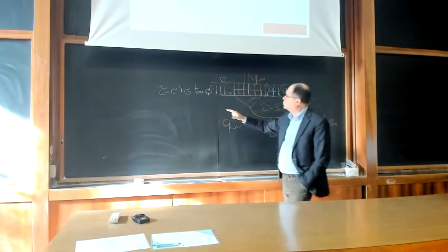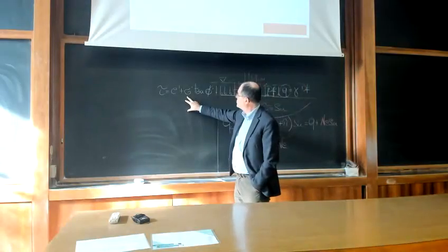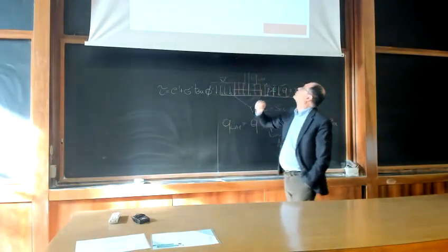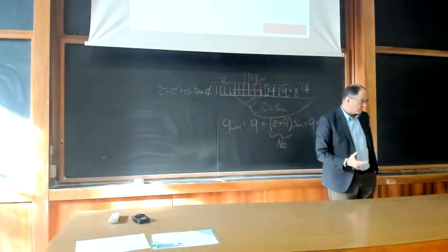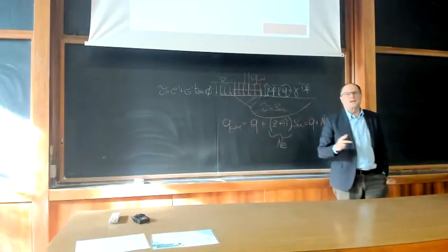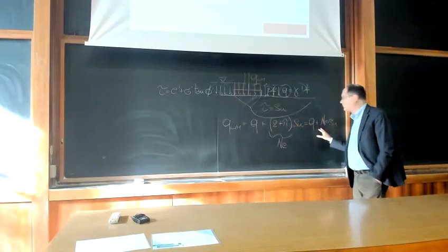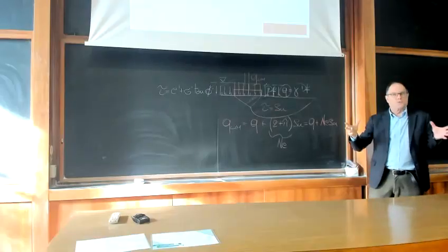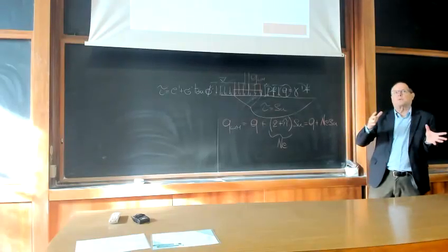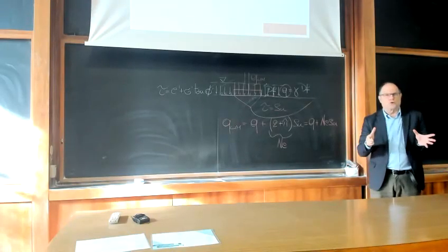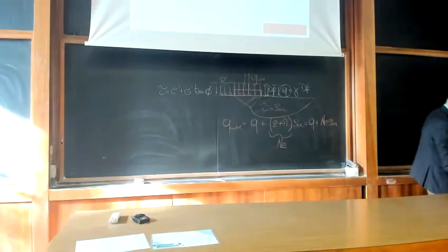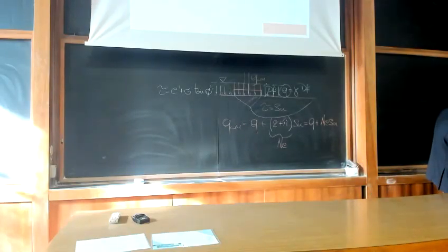So once you move to drained conditions, you have to consider also the soil weight and the gravity, and you are no longer able to find a true solution, to find the match between the upper bound and the lower bound solution. You have to consider separately the different contributions.